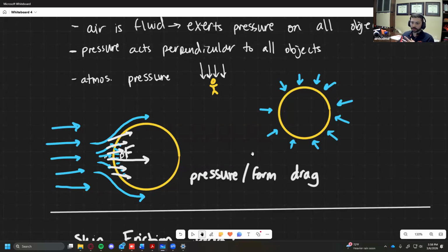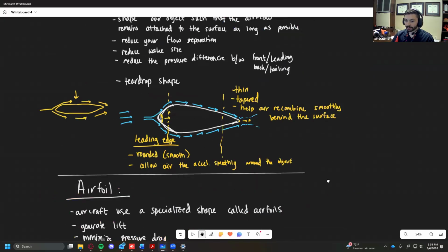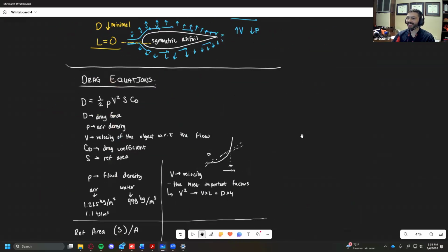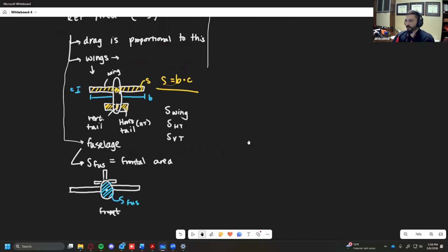Also, on top of that, one of the things that you have to fight though is you can't just have a stick for your fuselage, right? Because you can't have the thing break apart while it's flying. It can't wobble around, right? You want it to be stiff enough to survive. So you have to find some balance of stiffness to your actual drag, right? So that's just something to keep in mind. You do not want to make a pencil thin fuselage that will just snap if you pick it up too fast. So it's a bit of a balance there.